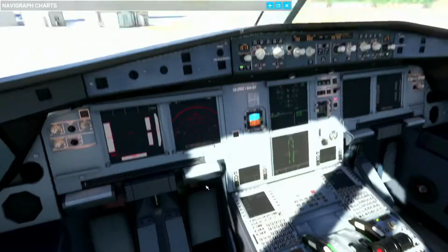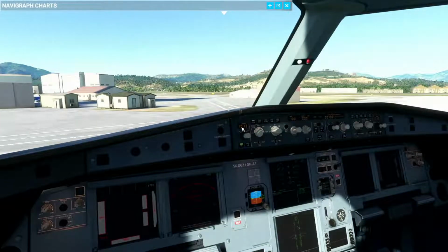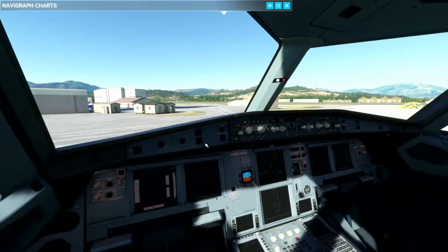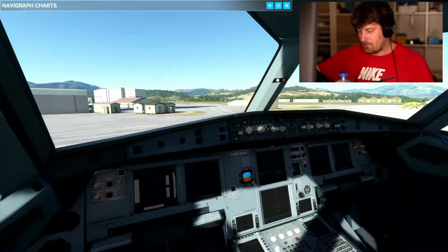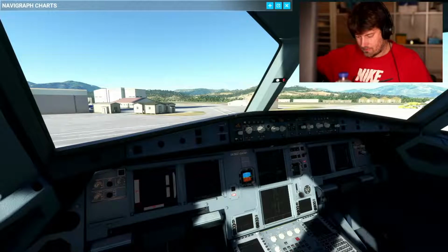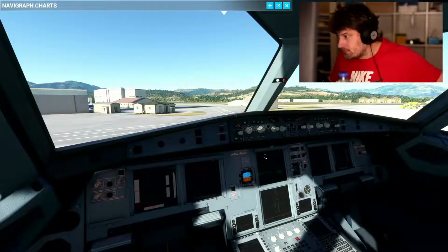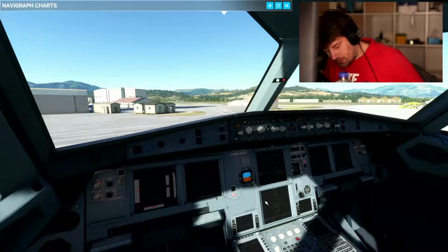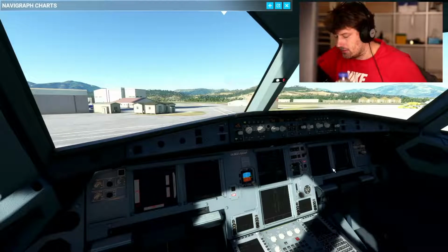What we'll also check is our constraints here on the FCU, left and right. And QNH we can also put in: 1026 in Corsica here. Alright. Once this has been set up, we can go over our flow in the overhead panel.